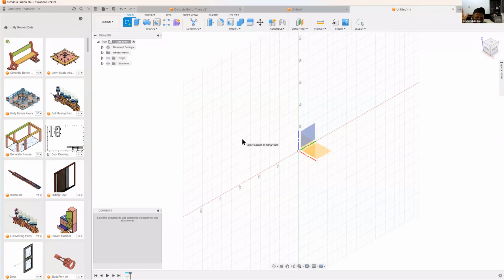But because sketching takes place on a plane, you have to choose which plane you are sketching on. To start with, we have 3 planes to choose from: either the XY plane, YZ plane, or ZX plane. You can choose any of them. Now, that is just at the beginning. It is possible for you to select another plane. You can construct a different plane from all of these ones and do your sketching on that plane. You can draw on any plane.